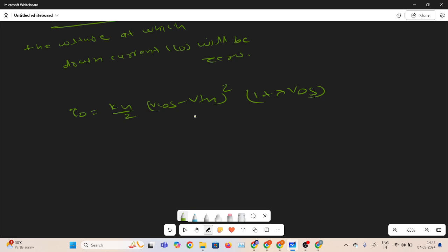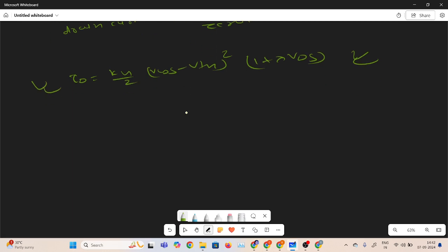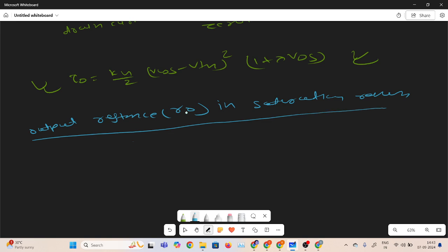So in this video, I discussed the first short channel effect, a second order effect, that is the channel length modulation. If you want to calculate the output resistance in the saturation region, you can write it. If you want to remember it, then no problem. In the DC analysis of the MOSFET, you need this expression. So here I am directly writing the output resistance of the MOSFET in saturation: 1 by lambda into ID, where ID is ID sat.